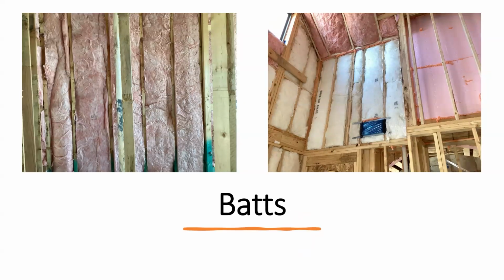So looking at both of these photos, we see that small differences in installation quality are enough to lower the grade from a grade 1 to a grade 2. So looking at that, the verifier now needs to look at it and determine the percentage of gaps, voids, and compressions, and accurately record the grade of insulation. So looking at the pictures that RESNET sent out, would you determine that the one on the left is grade 1 or grade 2? I personally would grade it grade 2 on the left, and I would grade it grade 1 on the right.